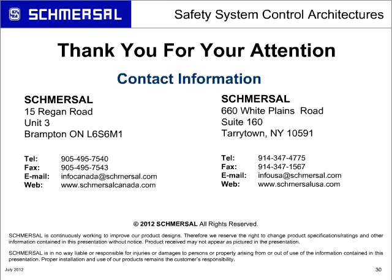But it's an RFID safety-rated switch. The safety-rated RFID switch typically gives you two solid-state outputs, similar to what people are familiar with the outputs of a light curtain, and that runs into your safety relay. So whether it's 1, 2, or however many, you can still achieve up to a control category 4 using that RFID switch. If I misunderstood the question, please type it in again, I can clarify.